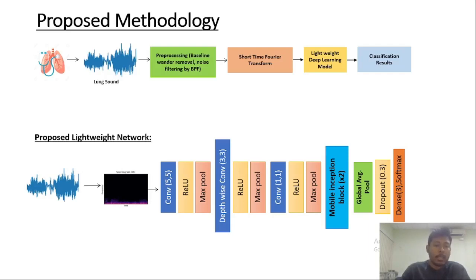After that we have noise filtering using a normal Butterworth bandpass filter, and after this pre-processing we have a block of short time Fourier transform, which is a time frequency representation. Given these short time Fourier transforms, we treated them as three channel images. Short time Fourier transform gives a single channel image format. We replicated the same output data into three channels, so we can get some feel of RGB images by projecting the single channel image into the magma color map.